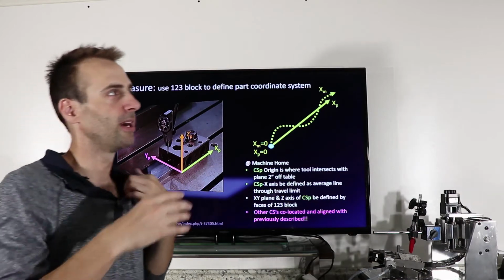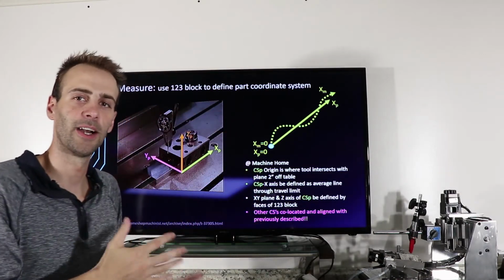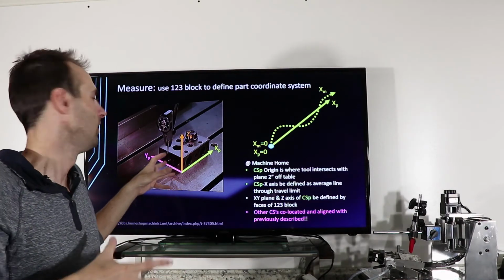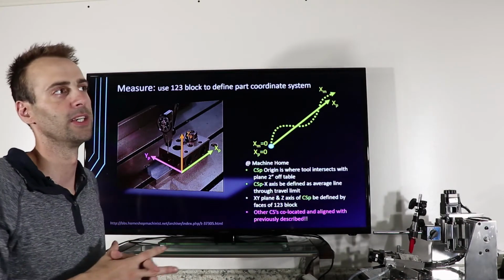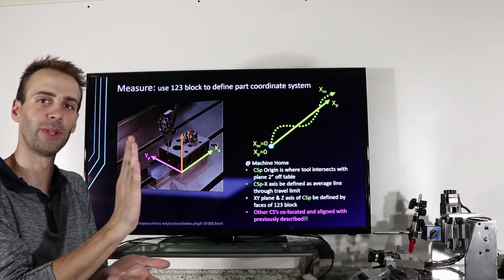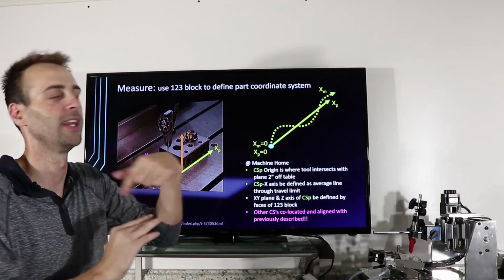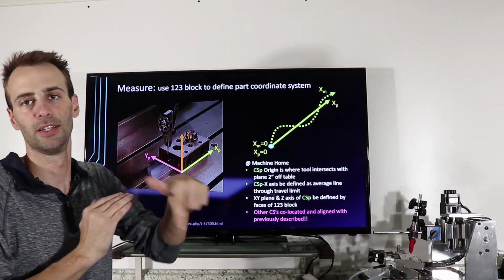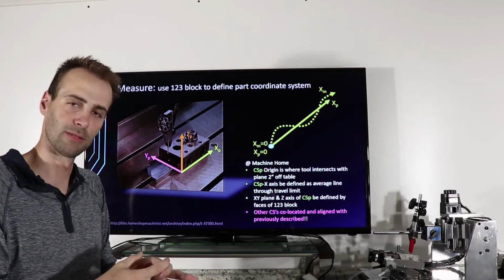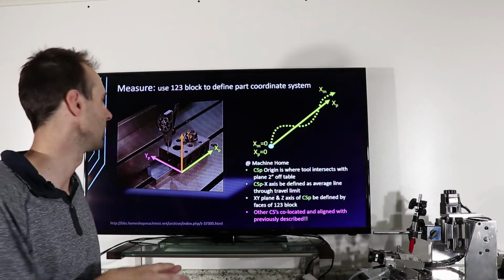And usually my parts are not as tall as they are wide, so I'm going to choose to lay this thing down, and that's why it's in this orientation. But maybe your machine's different. Like with a 3D printer, I normally stand things up so that every time I do a layer, it's as small as possible so I can build this thing up faster.